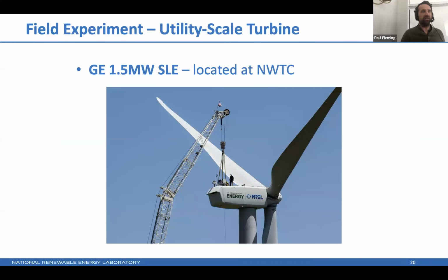And like that, it is making this rosette pattern of scans. And then what we did is we overrode a little bit, or tricked the turbine into holding different yaw positions to see if the wake moved in the way we expected to from our analytic models and from our work with LES. And so we ran cases where we did scans. So each of these rows is a different yaw offset that we held, while each of the columns is a different distance downstream from the turbine. And what I'm showing here is where FLORIS expects the wakes to be in each of these scans.